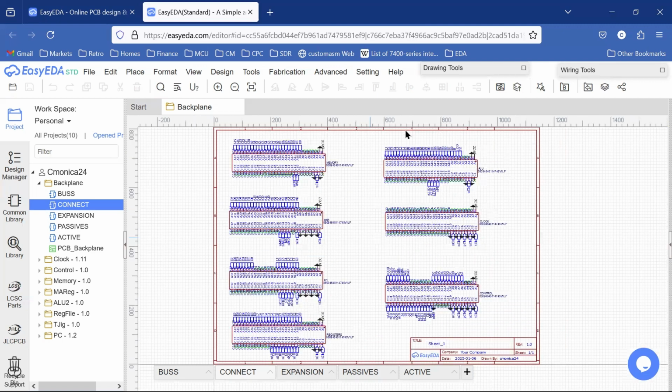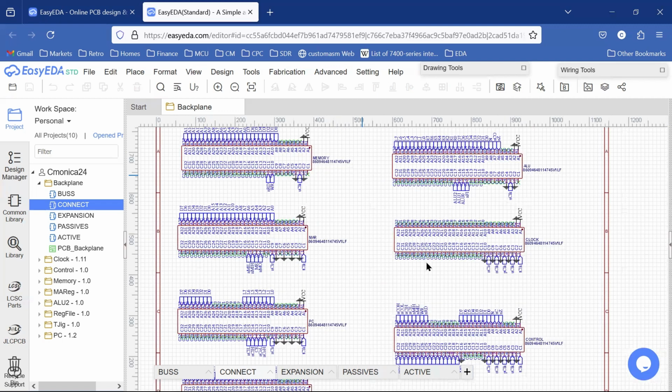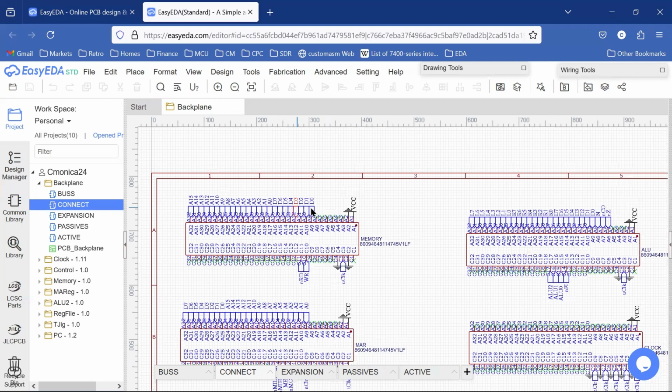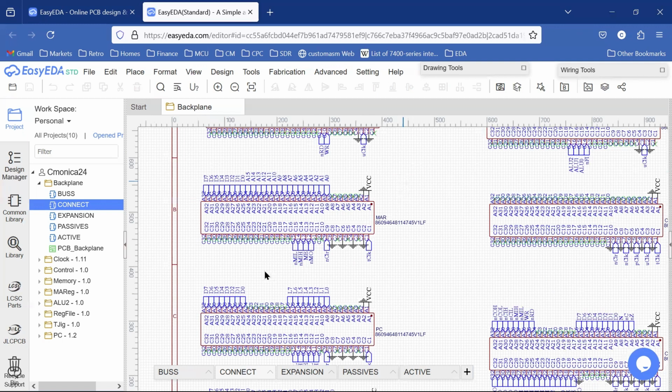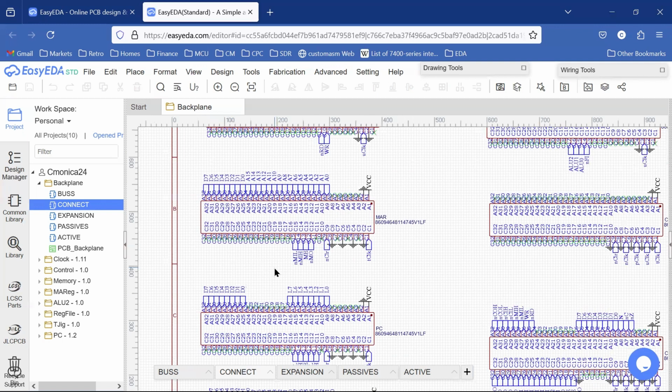The next item was, I started out here with the connections. I brought in all of the connectors together, and you start to see a potential issue here with, again, dealing with decisions that we made. We said here the data bus connections are here on this card, but the data bus connections are here on this card. A0 to 15 is here on this card. The address pins are here on this card. So you can see, we start to have issues like that where the cards were not all completely standardized.